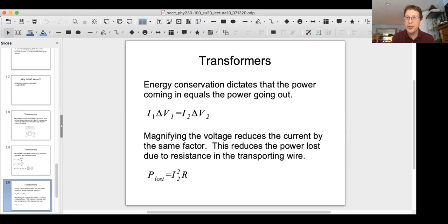But if you're talking about a few hundred miles of copper wire, the resistance adds up to something noticeable, and then the energy that's taken out of this wire adds up to something noticeable. So line loss is equal to I squared times R. And you want to minimize that value if you're setting up a transformer going to a long-distance wire. You want to minimize the current going across that wire to minimize the amount of power that's lost in the wire. So at the power station, you have a step-up transformer converting the input to high voltage, low current.